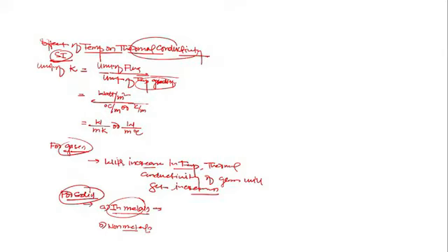So when we are increasing the temperature of metals, listen, if we increase the temperature of metals, then vibration increases. The molecules on their lattice will vibrate more violently at high temperature, and that vigorous vibration will hinder the flow of free electrons. Yes or no? Because when the molecules on their position start to vibrate more violently at higher temperature, then obviously they will hinder the flow of free electrons. And since we know that 90% of the energy transfer in metal solids is through flow of free electrons, which has been disturbed by the lattice vibration, with an increase in temperature the thermal conductivity of metals decreases. Clear?